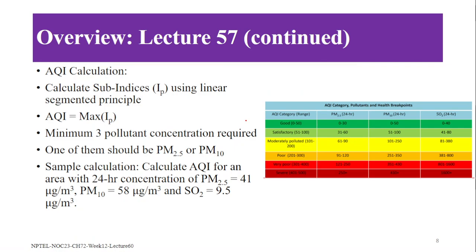So a sample calculation of AQI is shown here. This was also discussed in the lectures. I am just simply reiterating what was done in the lectures. Firstly, we need to calculate the sub-indices IP using the linear segmented principle. Then the AQI will be the maximum of the IP.